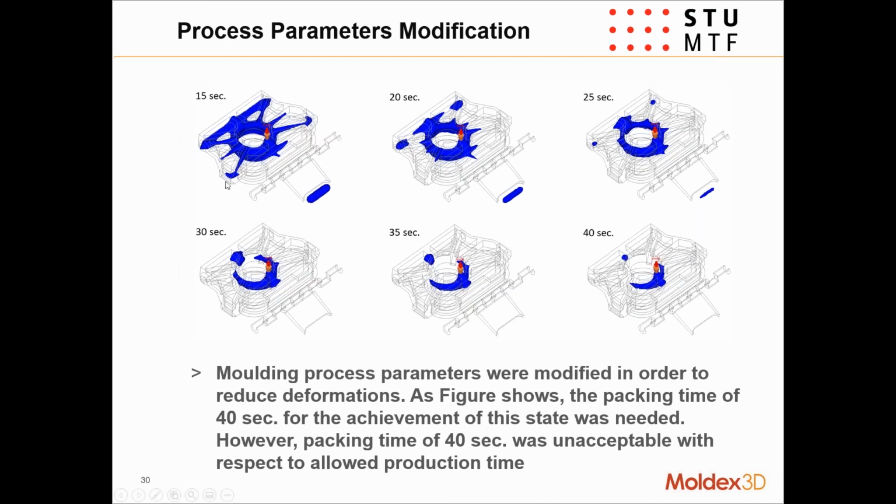This is a resultant Moldex3D result that you can show, and this is very similar to the trend that they would see in reality if they were to cut it open and take a temperature gun to it. This is something that we can show very easily, and as they increase the amount of packing time, you can see that this molten core gradually reduces, but it's not until 35 to 40 seconds into packing that this material has cooled down sufficiently to remove the possibility of having any sort of void in there.